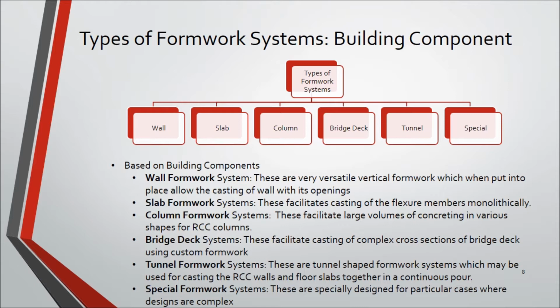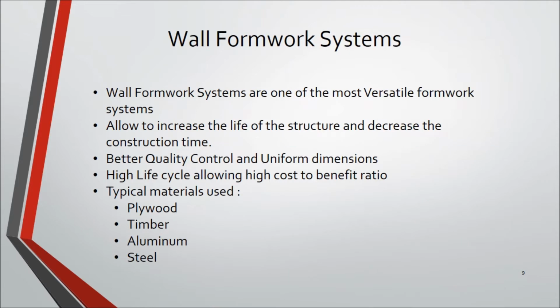Third, column formwork facilitates large volumes of concreting in various shapes for RCC columns. Fourth, bridge deck formwork facilitates casting of complex cross-sections of bridge deck using custom formwork. Fifth, tunnel formwork are tunnel-shaped formwork systems, which may be used for casting the RCC walls and floor slabs together in a continuous pour. And finally, special formwork are specially designed for particular cases, where designs are complex or very repetitive.